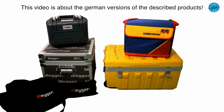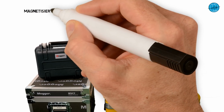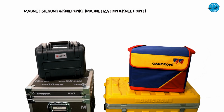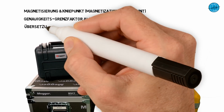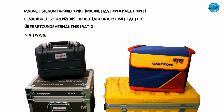In the first step, we briefly introduce you to both devices and then show you what experience we made in the determination of the magnetization characteristic and the knee point voltage, in the analysis of the accuracy limit factor ALF, in measuring the ratio, and with the respective software supplied with the devices. At the end of the video, we perform the famous green meadow test.